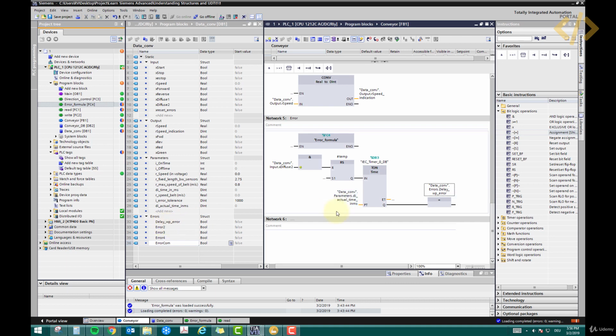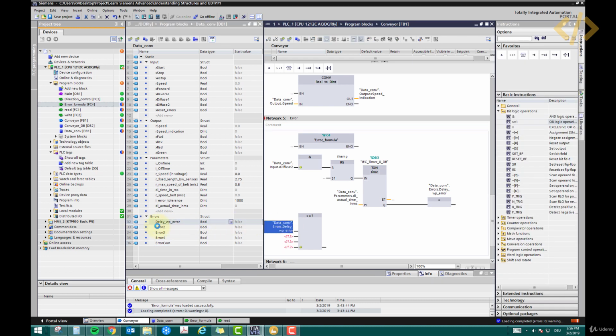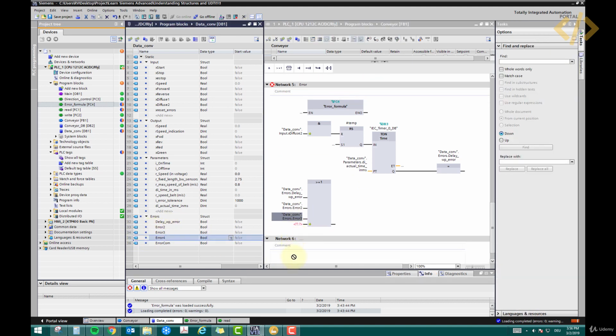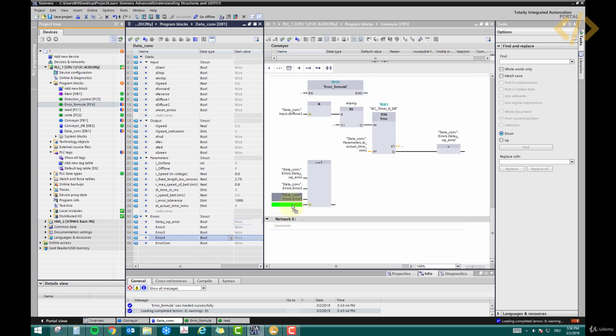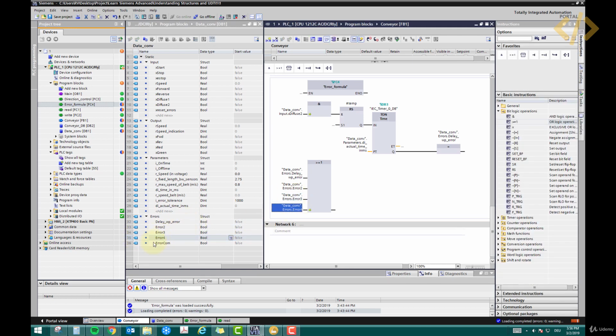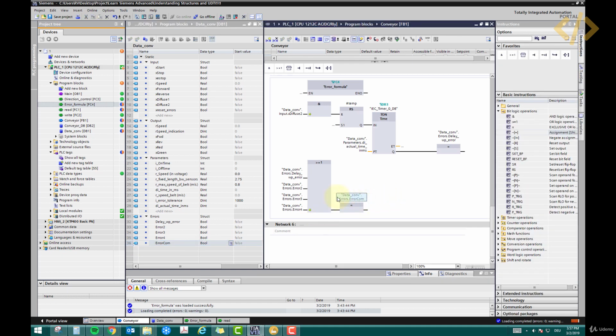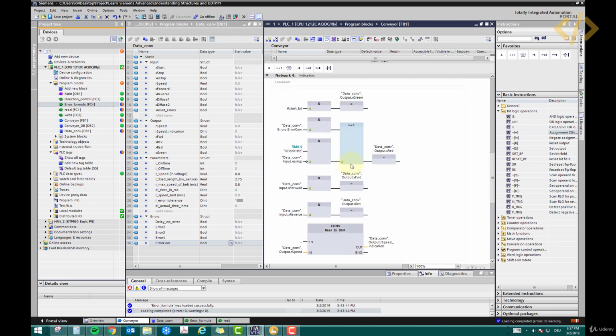So what we do is we make a small OR logic. Here I will take, if any of the errors is true. I'm using 3 and 4 because we haven't defined them yet, but maybe in future we talk about something and we realize, oh, we can also add this error. So I just keep it as reserved, and this will give output to the assignment, my error common. This error will automatically stop the belt.